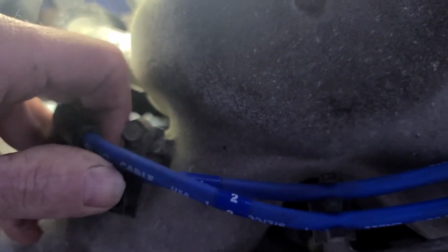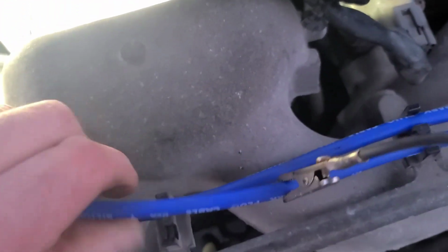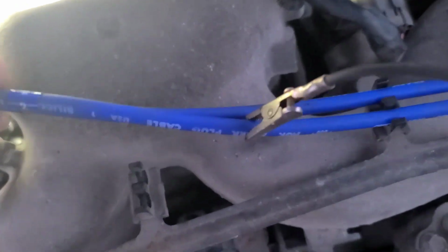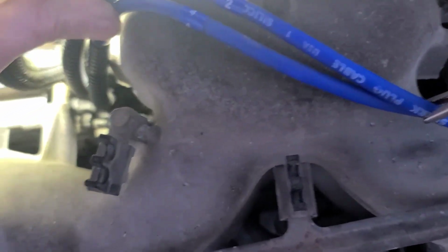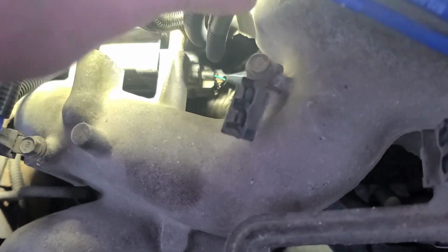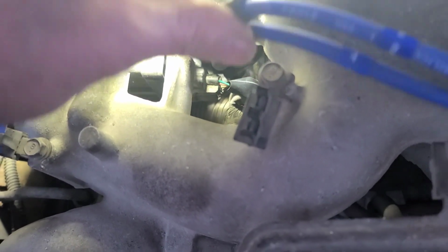I wonder if I should get a heat gun and heat this coil up and see if it'll... Because the customer reports that if they plug the car in, it starts and runs. And it only happens if it's below -10. I can maybe unplug that ignition coil and check for a trigger signal. I've got to look at the schematic and see how it works.